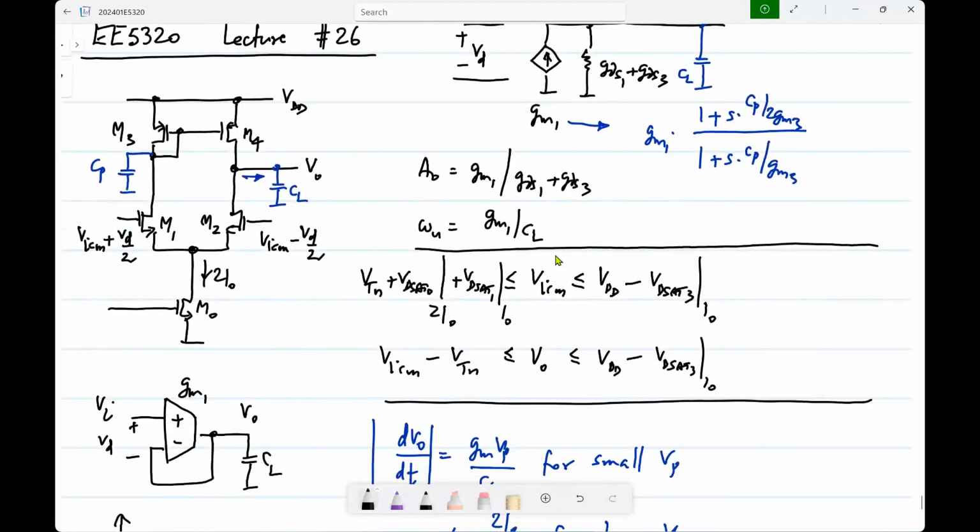Well, that is a separate complication we will not take. Depending on the bias voltages and so on, maybe for some, let's say the slew rate is so high that the input step you have to apply to get to that slewing area already also violates the other swing limits. That is possible. Okay, that is, you have to step this up so much that this one goes into the triode region. But let's take one thing at a time. If that's the case, you will know. That's all.